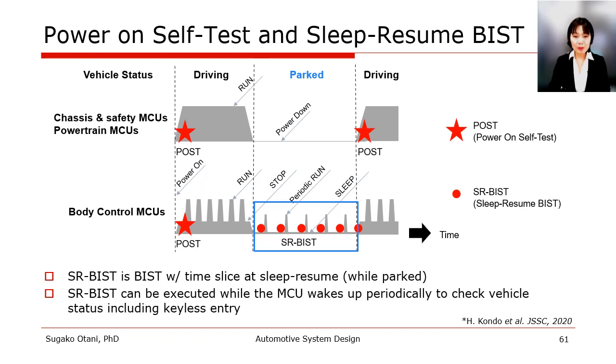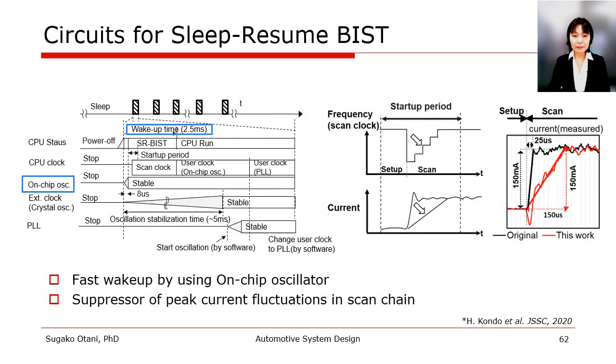To solve this problem, SR-BIST, sleep resume-based BIST, which is executed periodically in sleep mode, was proposed to enable BIST within the time slice while parked. SR-BIST can be executed while the MCU wakes up periodically to check vehicle status, including keyless entry. The SR-BIST is executed during the sleep resume period to avoid disturbing the CPU processing period. The SR-BIST is required to meet the limited test application time.